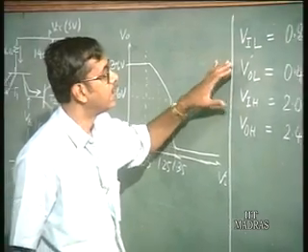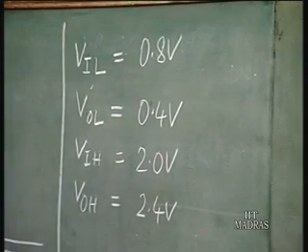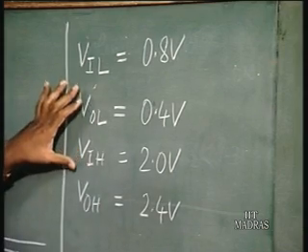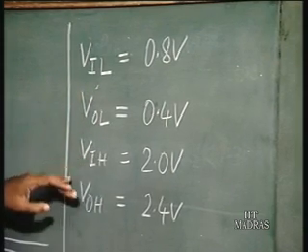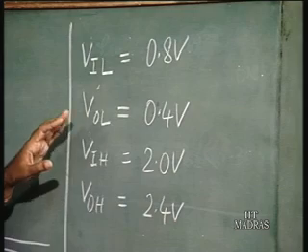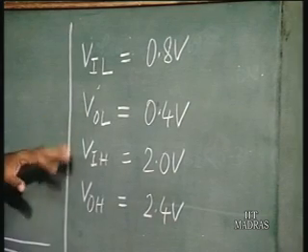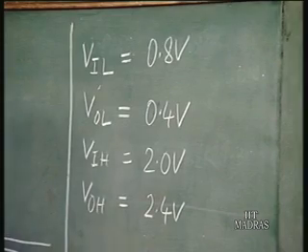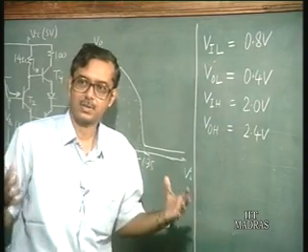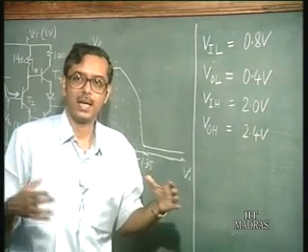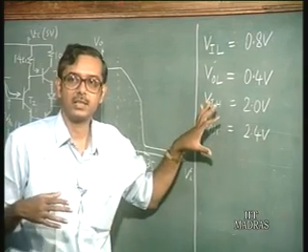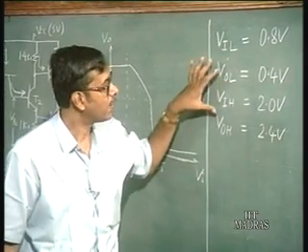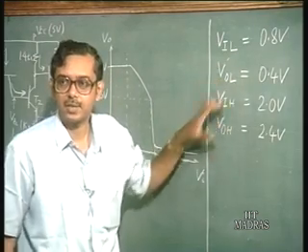If you look at these specifications, you will find that they are very conservative, in the sense that if you look at the characteristics, one could give a better description, you could put VOH at a much higher value and so on. But the reason they do it is that they manufacture a large number of chips in batch processing, and if they give very stringent conditions, they will have to reject a lot of their output. So these values are more conservative.